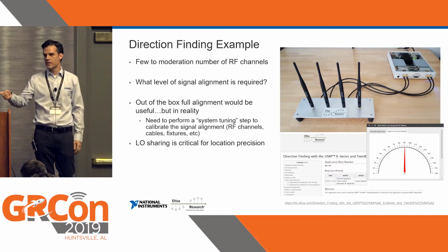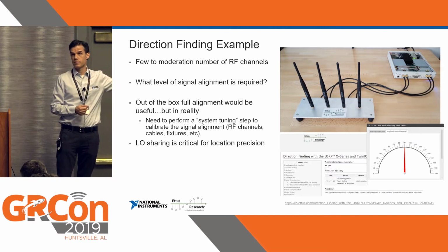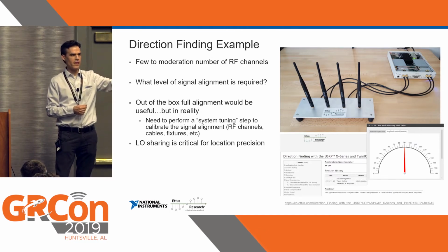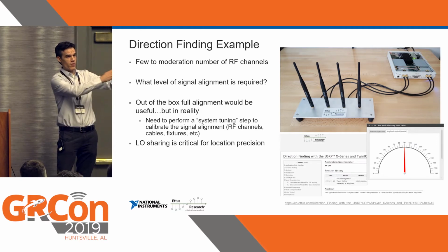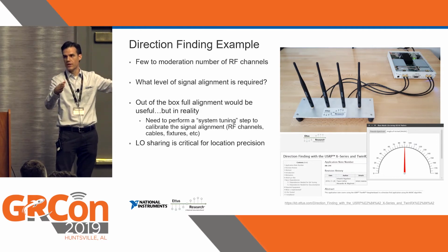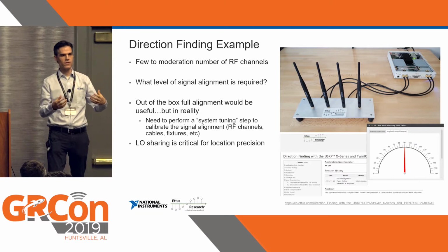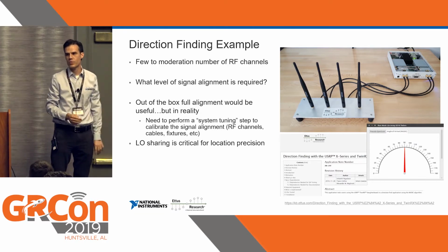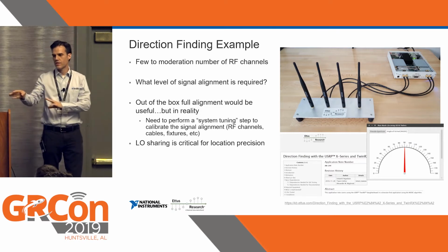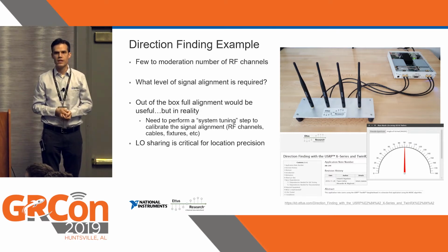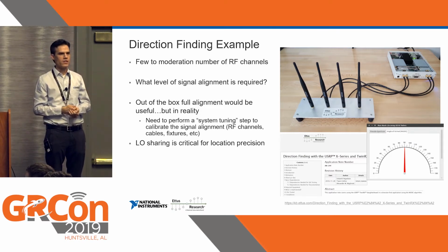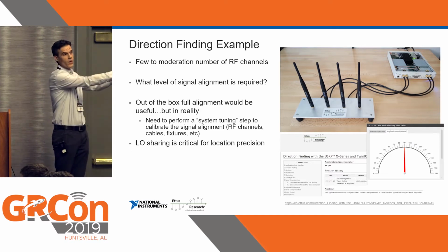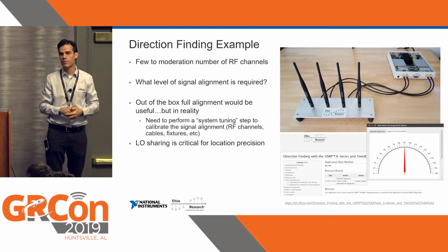Well, if that signal is coming in from your right, then the antenna that's on your right is going to detect that RF energy first before the antenna that's on your left will detect it, right? So you can get a sense of, oh, okay, the wavefront's coming through, and then tuck, tuck, tuck, tuck, tuck, tuck, tuck, it hits all the antennas, one right after the next. And so this example uses an algorithm called MUSIC that basically looks at the time of arrival of when the signal hit each of the antennas to figure out the angle of arrival of where it was coming from.